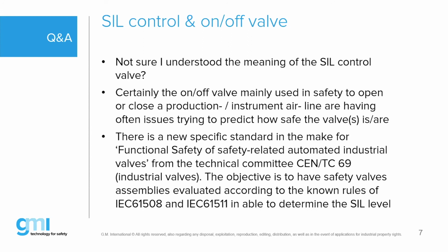And actually we were using accreditation officers, those assessment engineers, who were using part of the 61508, part of the 61511, a bit of a mix of both. They came to statements saying, well, maybe that smart positioner is SIL X, or maybe the actuator is SIL X, but not the majority of all the valve assemblies could use a specific certificate for the complete functionality.